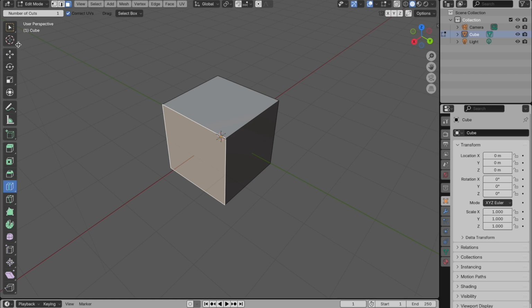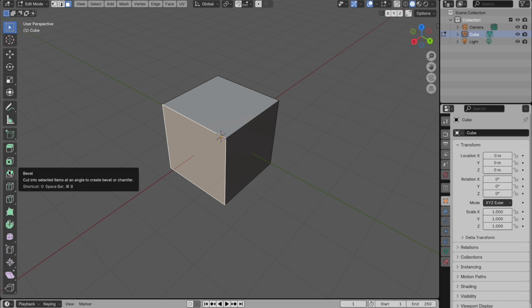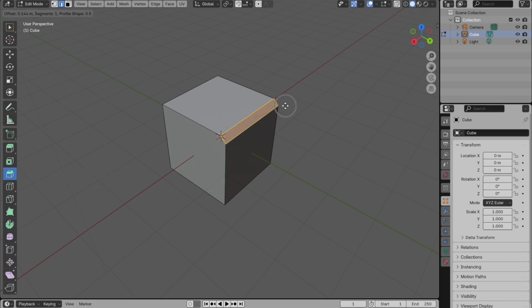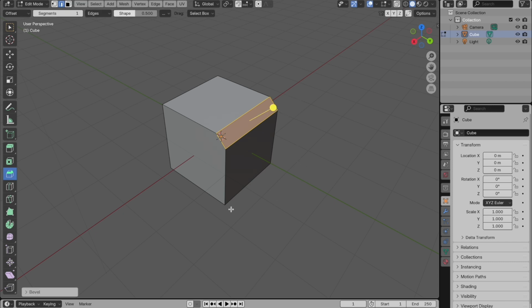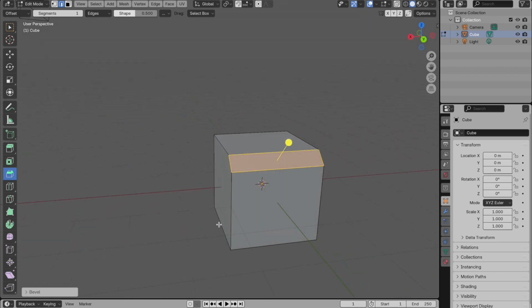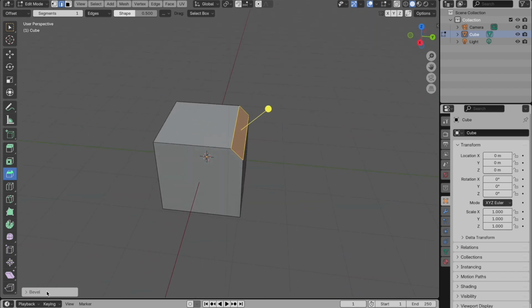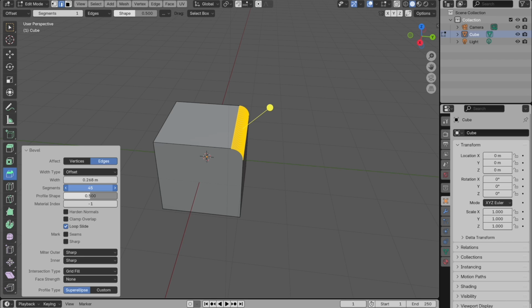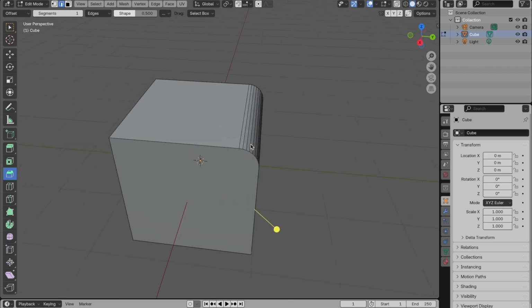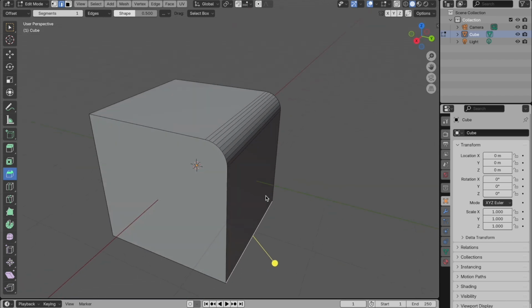And if you also press the bevel button, which is the last thing I want to be teaching you in this video, you can edge select and then click the bevel button, pull on that knob, and you will get some sort of smoother surface. And if you press on that drop down on the bottom left, you can increase the number of segments, which will make your edge smoother, and that's how we achieve a smoother look.